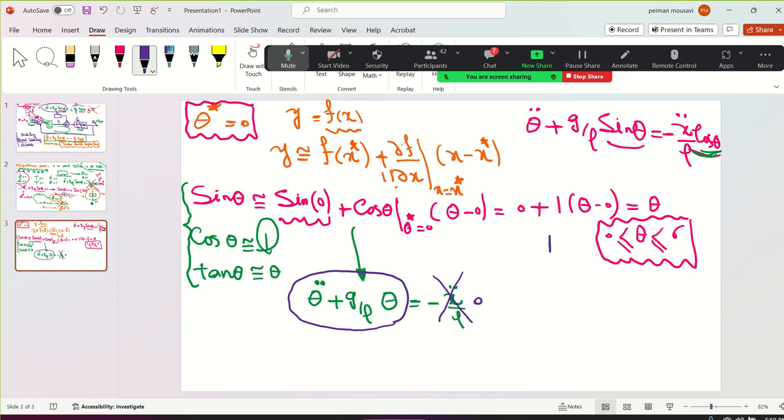What does it mean? I'm going to translate it physically for you. This is the pendulum, the same problem. I just remove the disturbance. I only deflect it from the equilibrium point and release it. Why am I doing that? Because I'm teaching you about the stability, marginal stability, and instability of the system. So let us do that together. When I go to MATLAB and coding, I'm going to include that and compare the linear differential equation and the nonlinear differential equation.